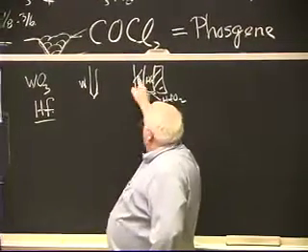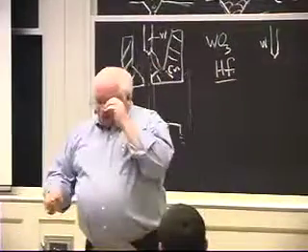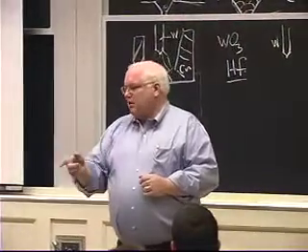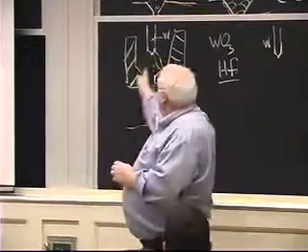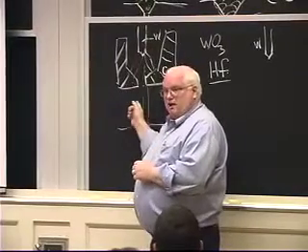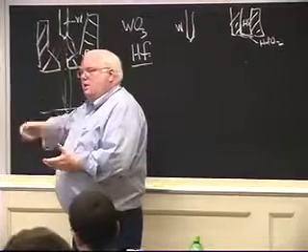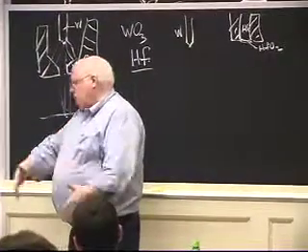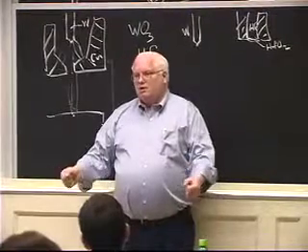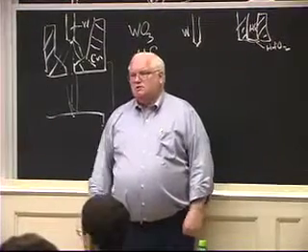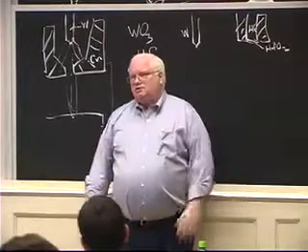Okay? And now you can run air in this. And so now for $1,000 or $2,000, you can buy a little plasma cutting torch that will cut sheet metal, and I mean sheet metal maybe up to 1/4 of an inch thick, by just using compressed air as your gas flowing through. Yes, you do have to generate a gas, otherwise what's expanding, what's shooting through? They used to use argon, and they still use argon in the heavy section plasma cutter. So I have a plasma cutter in the lab that'll cut up to an inch thick, but it looks like a big old welding power supply, almost the size of that cart. But it's also generating 400 volts and 100 amps, okay?